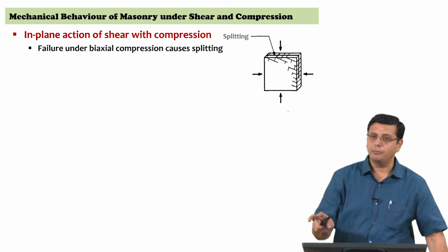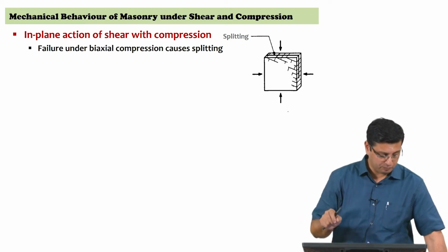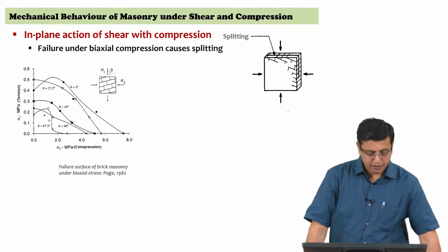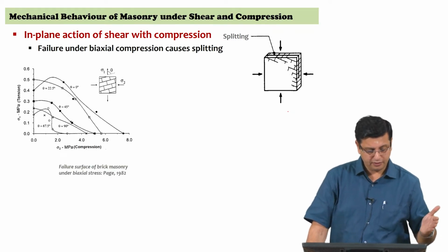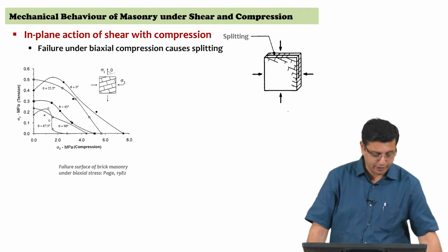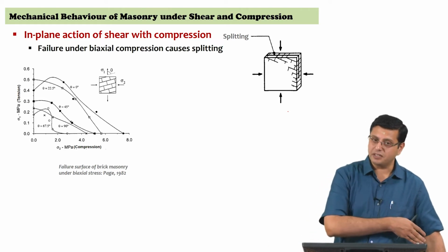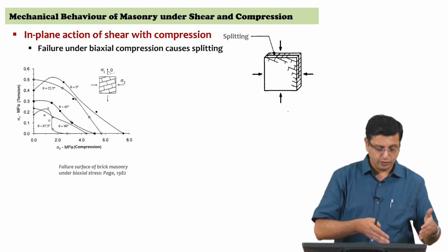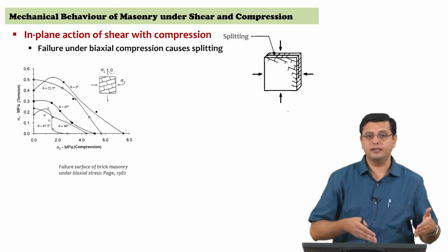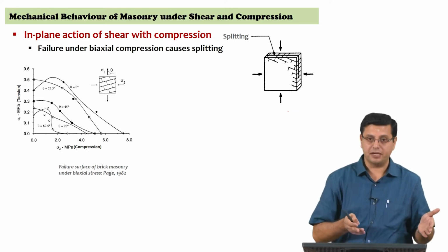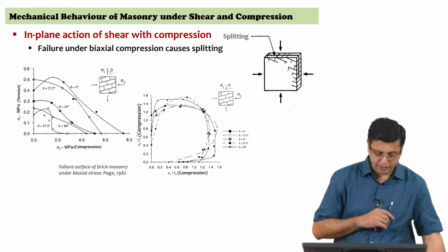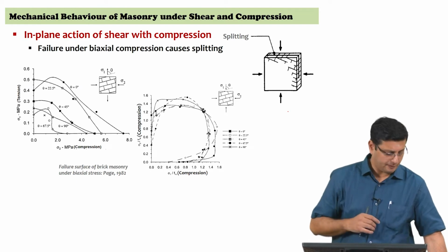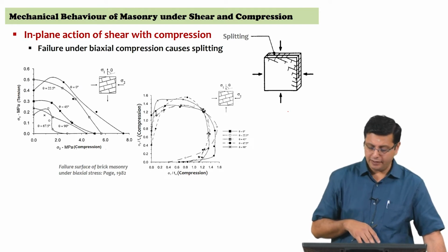This is a possibility given the multiple materials, multiple strengths and stiffnesses that we use in masonry. So, for the tension-compression sigma 1, sigma 2 three-dimensional graph that you saw in the previous slide, if you were to collapse it, you can see that none of those failure curves actually overlap or have the same shape.